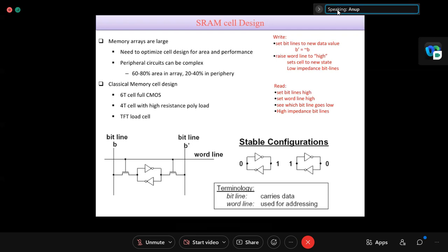So tying up, yes, logically this is correct. Whatever Goswami sir told, that is correct. So this could be done for NAND gate, and for NOR gate, I mean that legs could be connected to 0. Whenever we are connecting it to 0, then the dynamic power that you are talking about will not be there. And then the leakage will be reduced. So many pros and cons are there.